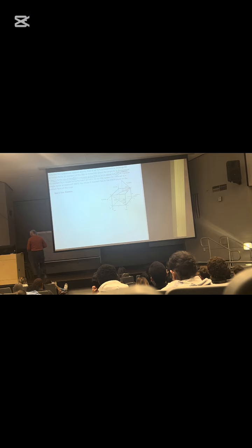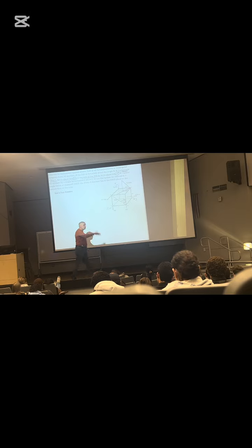Check the coordinate system. Because if I change this to Y, Z, X, now what you've landed on is the X component. So if you're just thinking it's the same coordinate system that's in the Hibbeler, because Hibbeler uses one and only one coordinate system, and I told you what I can do? Use any coordinate system as long as it obeys the right-hand rule. If it obeys the right-hand rule, I can throw in any coordinate system. That's why I tell you in a 3D problem, always check the coordinate system.